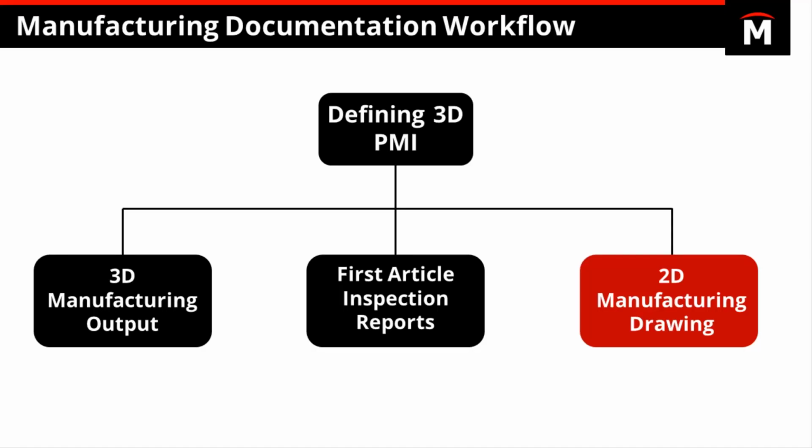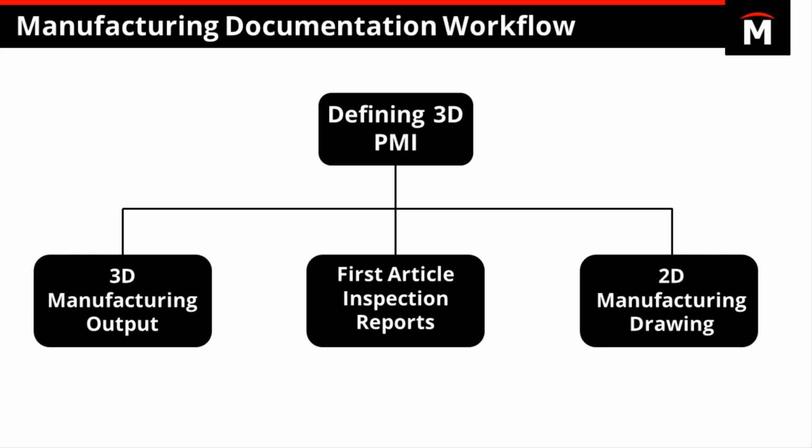So I was able to create the beginning of our drawing packet, again, in just a matter of minutes because so much work has already been generated for us in those 3D PMI and 3D views. So we covered a ton of information. We saw how we can define 3D PMI using DimXpert and MBD, and then how we can take that single source of information and export it in a variety of ways for documentation. We can export it for eDrawings, 3D PDFs, and then multiple ways using SOLIDWORKS Inspection and 2D drawings.